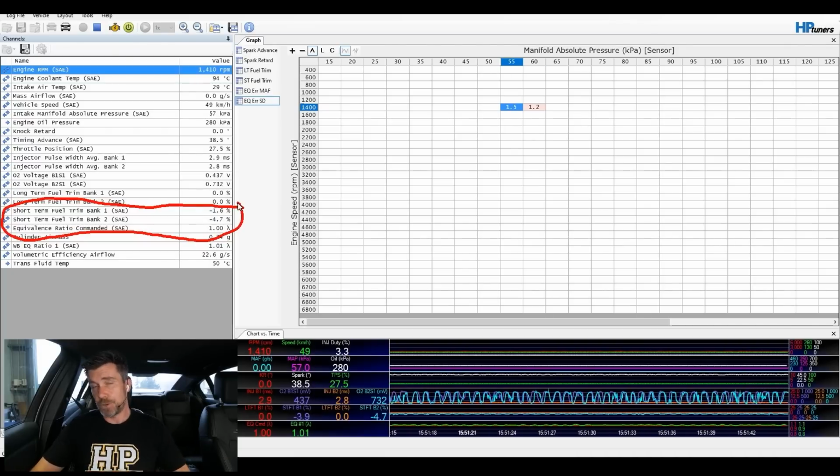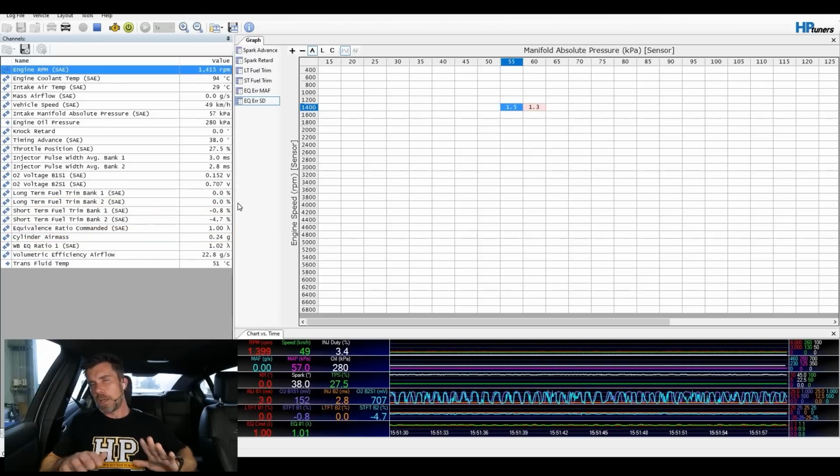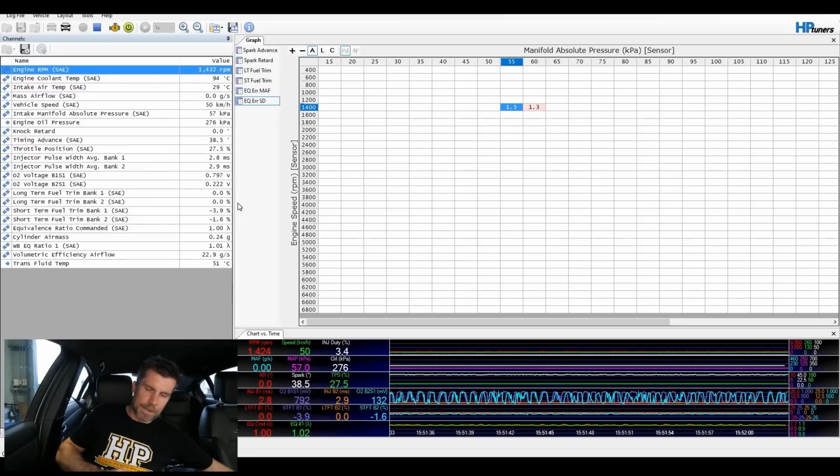Alternatively, if you do leave the short-term fuel trims enabled, you would need to change your math function so that it incorporates the correction into your calculation. So just important to mention, at the moment we're not seeing a true representation of this error because of our closed loop. As long as we understand that, though, it's perfectly fine for our demonstration. So let's gather some data here.